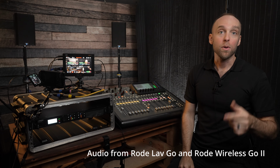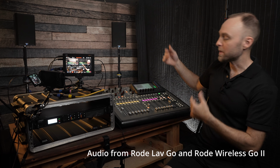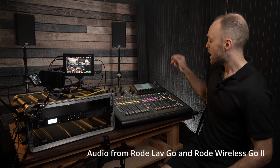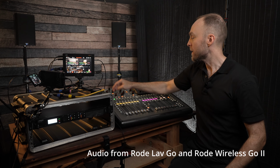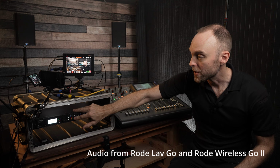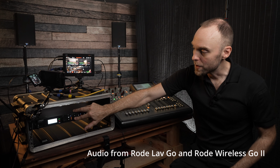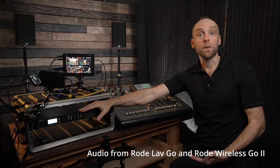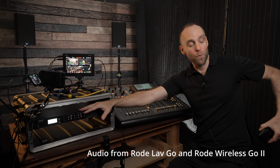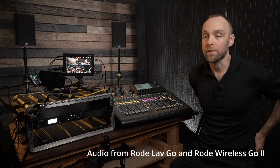All right, so you'll have to hear me on my second lavalier mic that I'm using to record, because I've got to turn the speakers down and turn down the level to the Video Assist. So I'm going to basically just set everything back to nothing. I'm going to turn down the receiver to 0 dB, which means the receiver is not adding gain or cutting gain from this wireless pack and this WL185, Shure WL185 that I'm wearing.